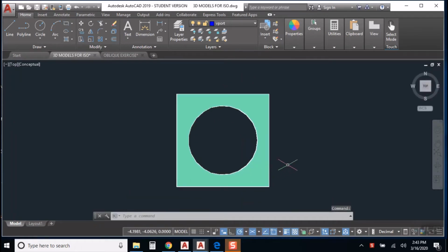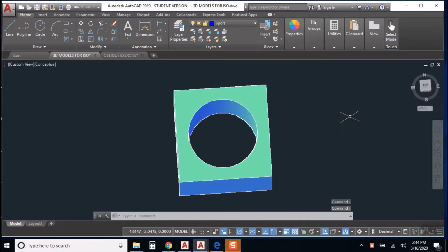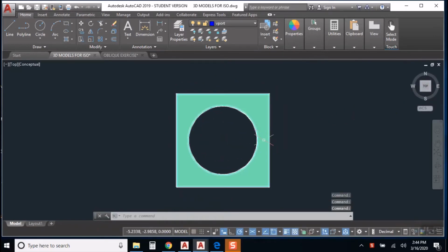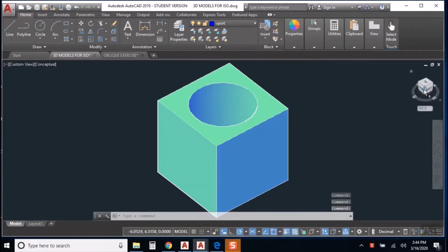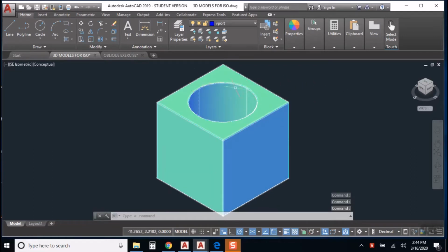Okay, welcome back to our final discussion about isometric drawings for our first day. What we're looking at here is probably the most complicated thing about isometric drawing, and that's understanding that round things, circles, like this hole going through this block, don't remain circular when we look at them in isometric. We're going to have to change the shape because the angle gives the circle a different form when we look directly at it.